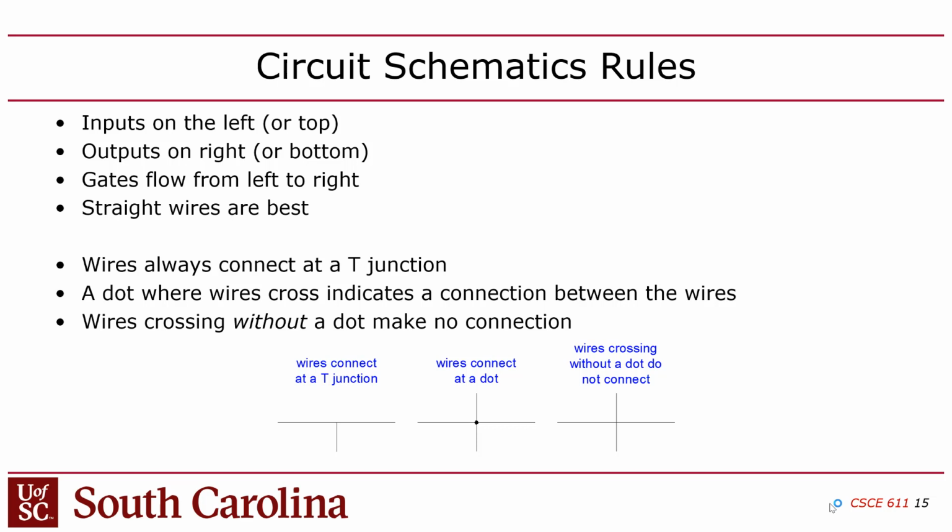Now you might say, wait a second, why don't we just draw the schematic in a CAD tool and then push a button and have the CAD tool generate the corresponding Verilog code that implements that schematic, so that way we can think of the design as a schematic and we don't have to worry about doing this bizarre conversion in our heads.